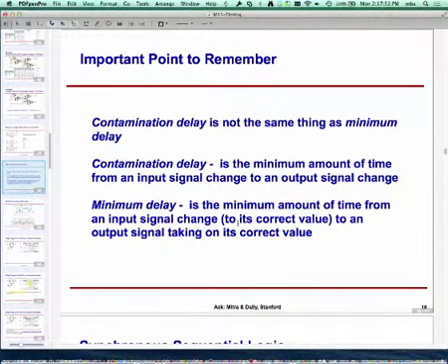For example, one copy of the adder may have a smaller value than another. An adder may have a smaller value under different temperature conditions. The same adder for some input values may settle earlier than for other input values. An adder may get a correct value, change again, then go back to the correct value. All of those things fall under minimum delay. So propagation delay is the worst case situation. After that, across all conditions, you're guaranteed it will not change.